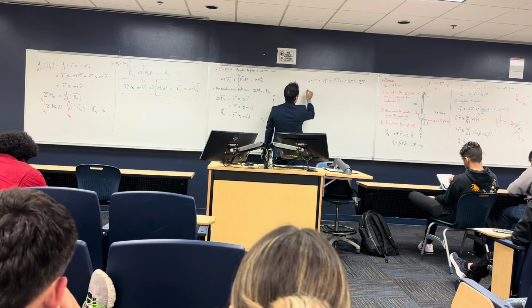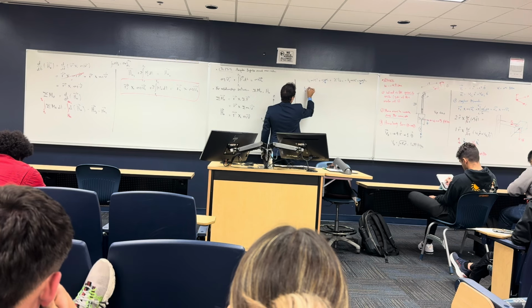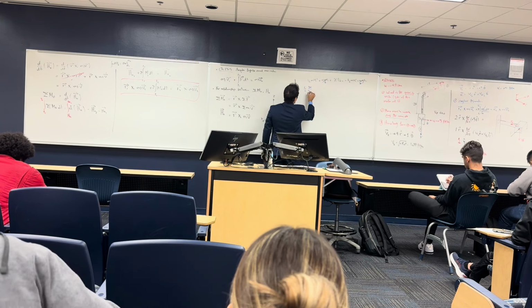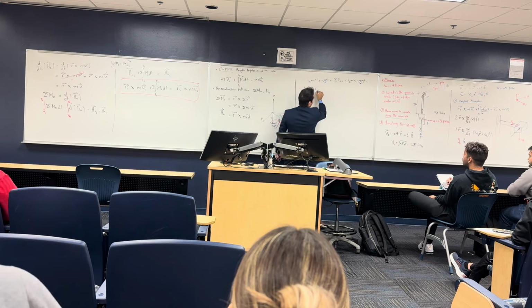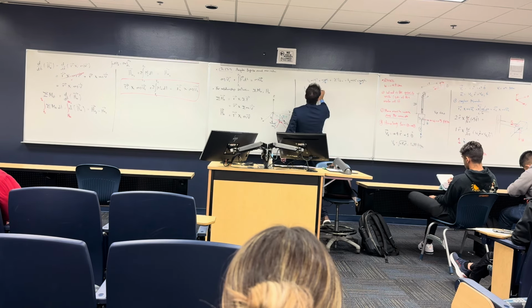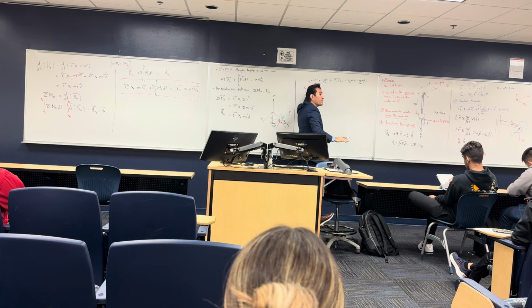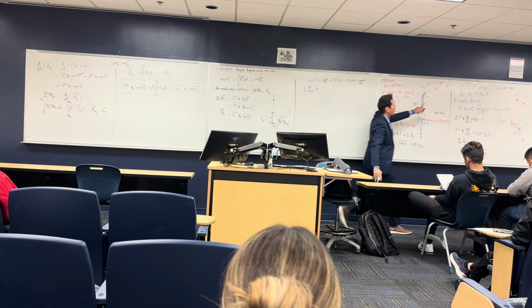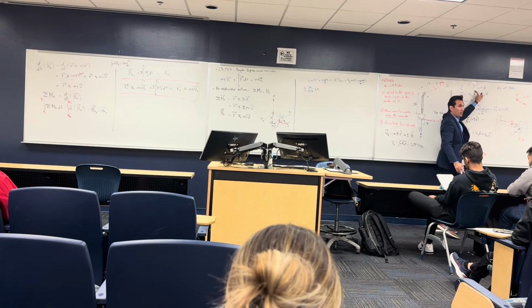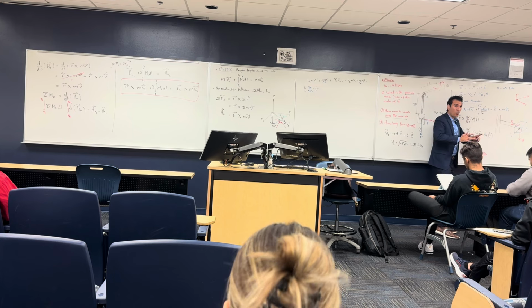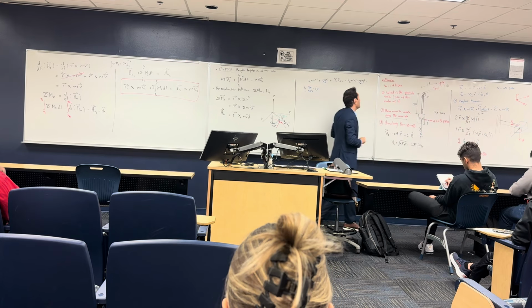I have half mv1 squared, so half 80 over 32.2 multiplied by v1 squared. v1 is 0.5, and actually when we say v1, this is the total amount of velocity, radial, so you need to get not the vector component, you need to find the scalar component. And with a scalar, because the energy is a scalar quantity, not a vector quantity, so everything should be scalar.